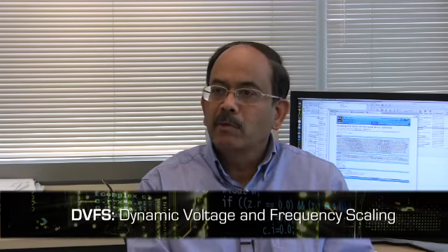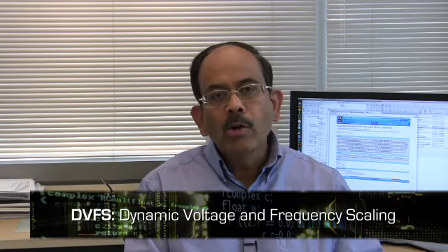There are a couple of technologies now available that can be used to control it. One technology is something called DVFS. Using this, you can actually change the frequency at which the processor is running. If the frequency is lower, the computer will run slower, but it will get less hot. And that's good, but how do you trigger that? Well, it turns out chips now have temperature sensors on them. So you can figure out, while the program is running, from the program itself, what temperature the chip is. And if it is getting very hot, then you turn the frequency down and it won't get as hot anymore.